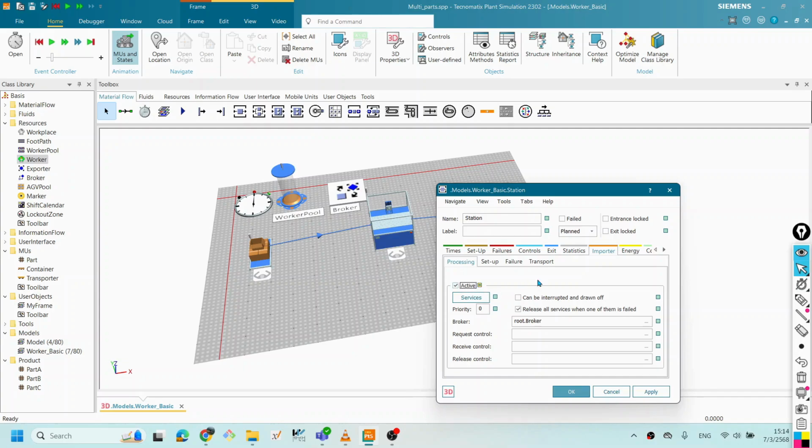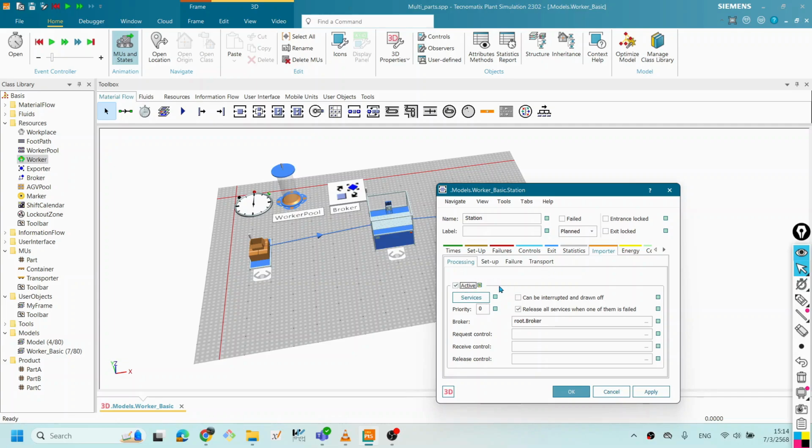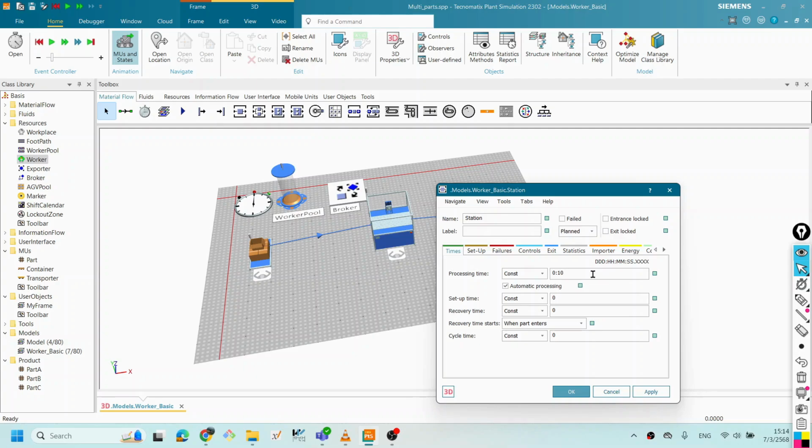I click on here, and the processing time is used here, right? 10 seconds for operating that machine by human. It uses just 10, and the 10 is counted in the importer. This is a manual machine, right? And this time I need to change it to 60 seconds. It's longer than 10. I apply the 1 minute, right? It's 1 minute. I just click OK, already done.